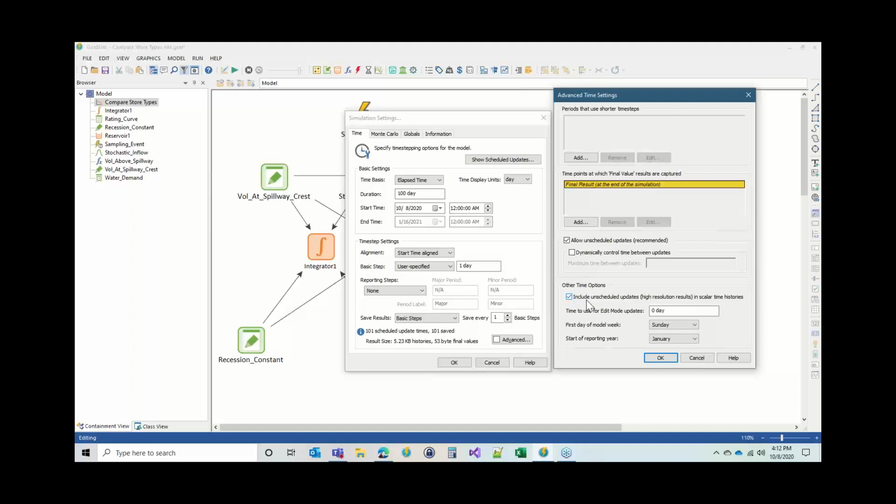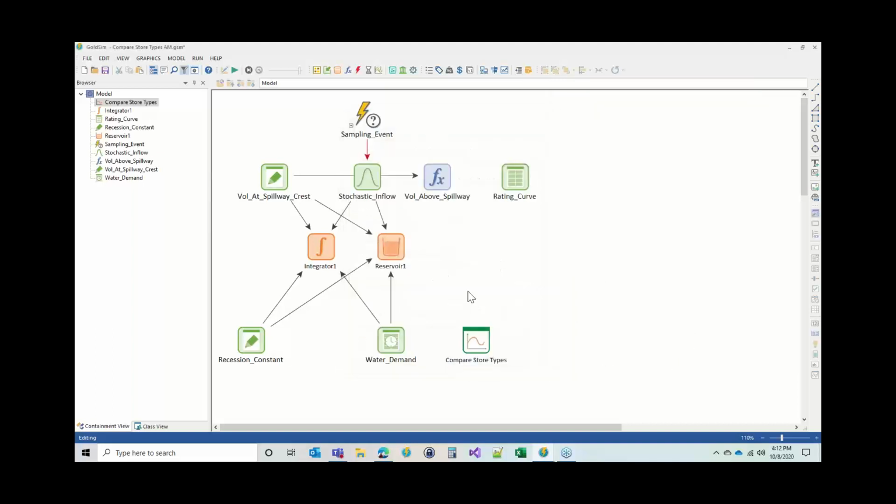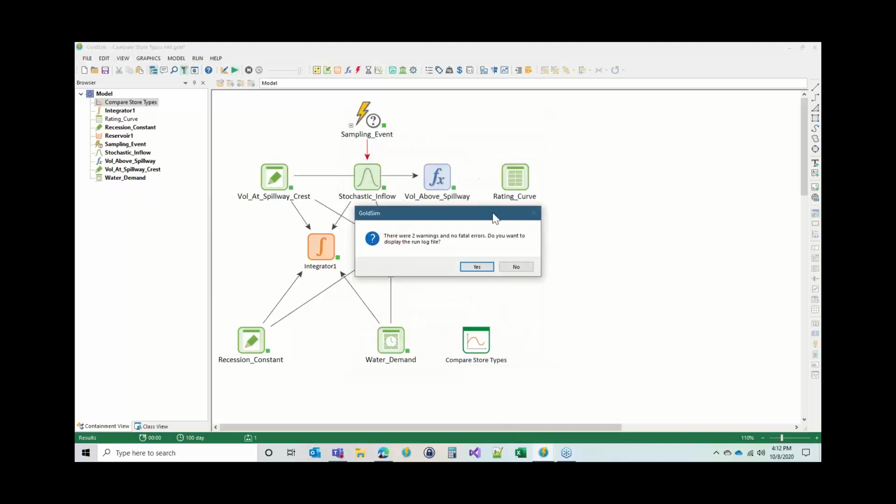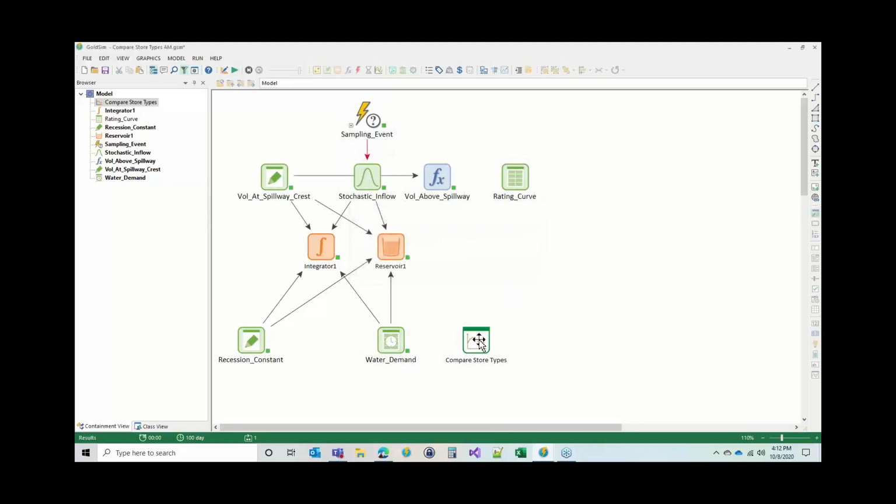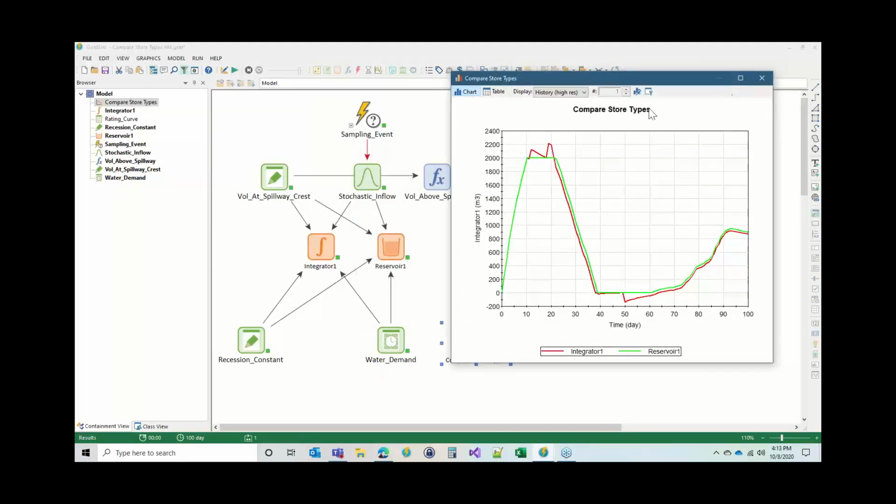And I very often get requests or questions from our users saying things like, I have an unexpected flow, or I'm not seeing a flow that I expect, or I'm not getting a good comparison with an Excel model, and it's usually because of this. It's usually because their bounds are inserting time steps and they did not realize it, and they're not accounting for it, or they are not seeing it in their charts. Because a time history chart by default does not show the values of the inserted steps.